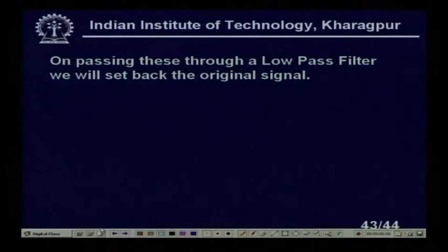The only problem with the state variable structures, we have seen, is that the high pass, high pass notch or low pass notch filter functions are achieved by making the coefficient of S in the numerator 0, and we have seen that this is actually done by signal subtraction. So, due to mismatch of any resistance or capacitance, it does not become 0, and that creates the problem. As you know, in the case of notch circuits, if you look at